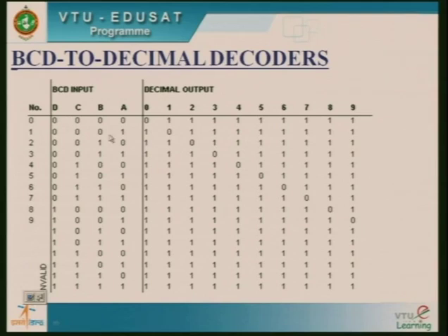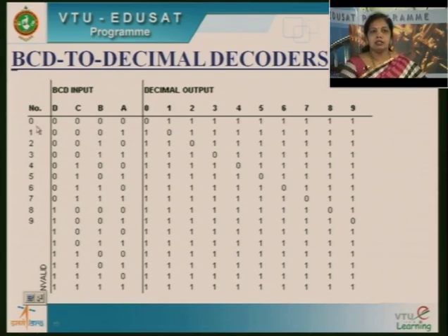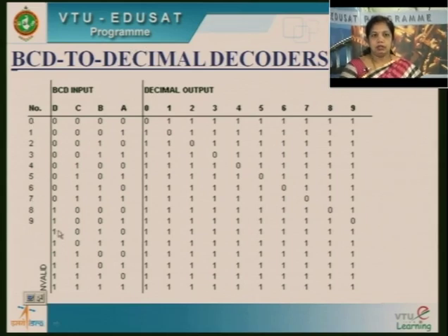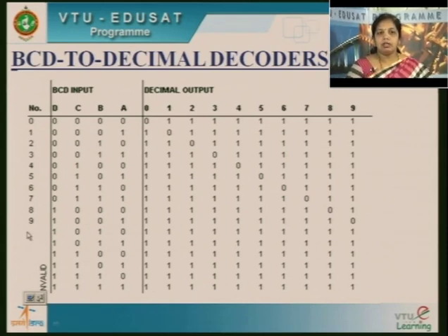You can see the truth table here. We have BCD inputs. Even though I have 4 control signals, which generate 16 combinations, we are going to consider only 10 here, since we treat this as BCD. BCD represents 0 to 9, so the inputs are from 0 to 9. I will not be using these other inputs. After 9, these are treated as invalid inputs.